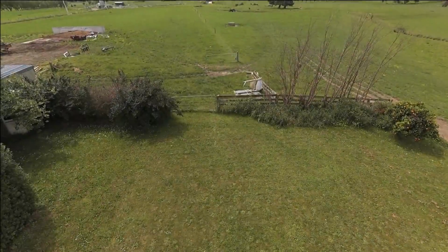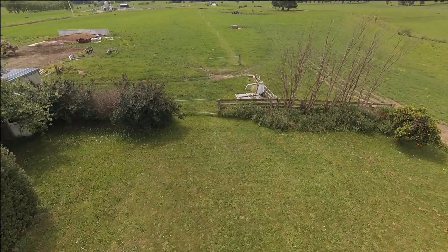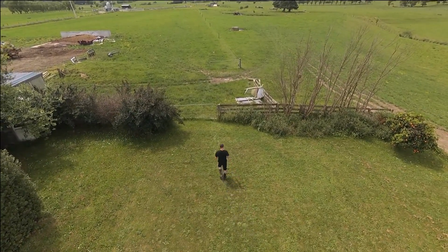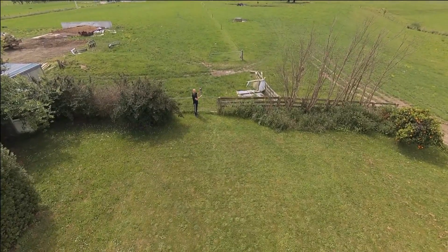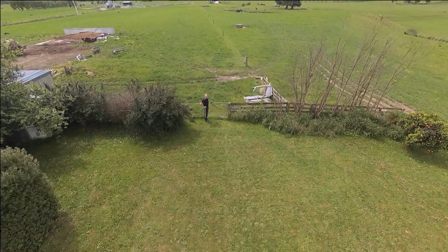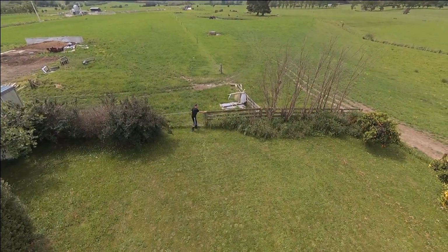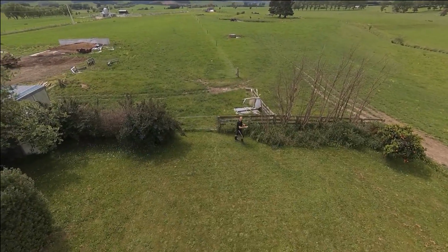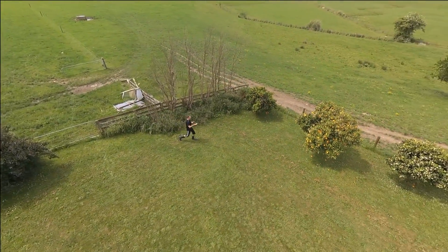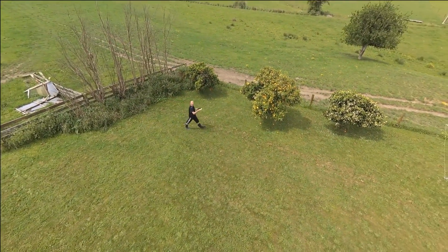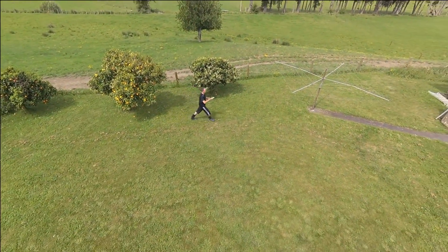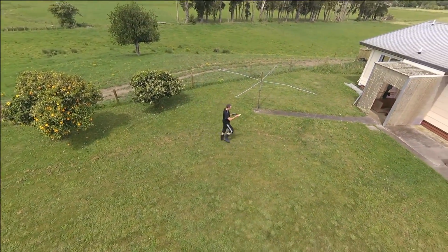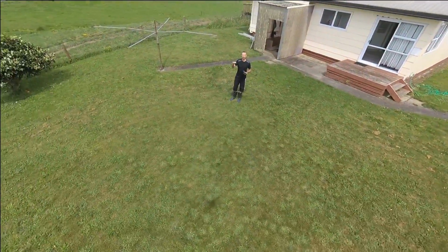Okay, now let's have a look at some of the modes that are provided by this new controller. First one is turn only, and you can see when I raise the transmitter up like this, I switch it on, and it moves a little bit. It's not supposed to move at all, but it doesn't move much. And then for the rest of the sequence, it just turns the camera without moving at all. So it's like a position hold, but it turns the quad and the camera to face the target.